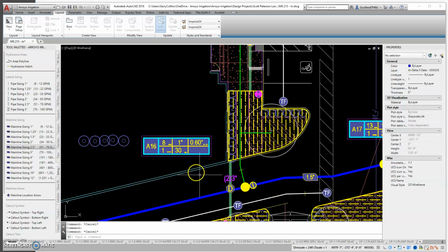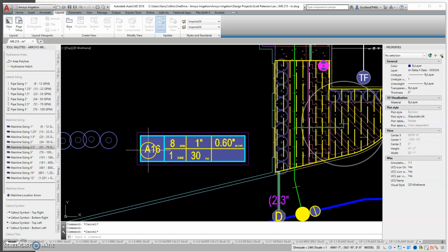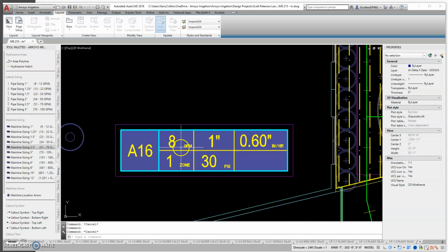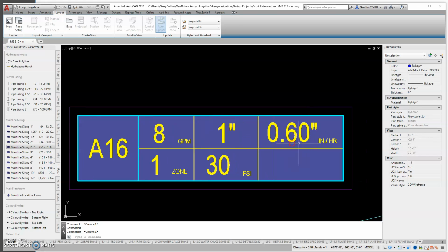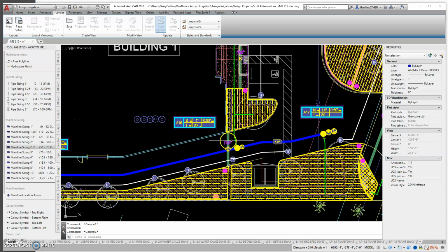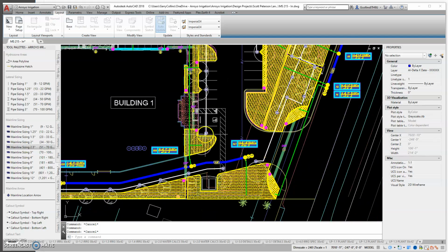And then you'll see here, each valve has a station ID. It tells what number it is on the controller, and the flow it has. This is a hydrozone number in our water use calculations. Then the pressure to operate this valve, the size of the valve, and then over here is the precipitation rate. We fill this out for each valve, and that's required.